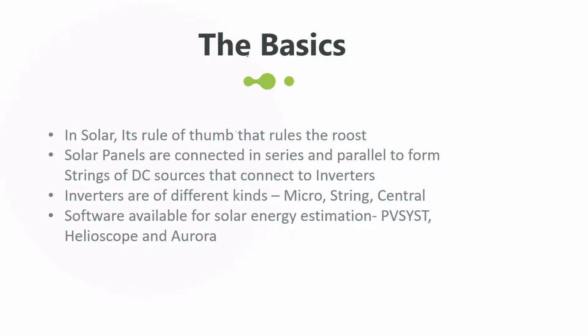Typically, for rooftop commercials, 400 kilowatt is an ideal size. Monocrystallines are also coming; the cost is almost coming closer to the polycrystalline. Earlier, a few years back, polycrystalline was way cheaper than monocrystalline. The technology had not yet matured enough. So that's another thing. And then the inverters, what type of inverters you're going to use.